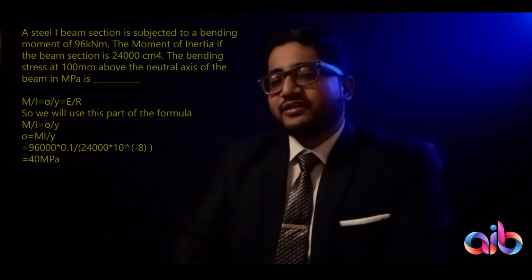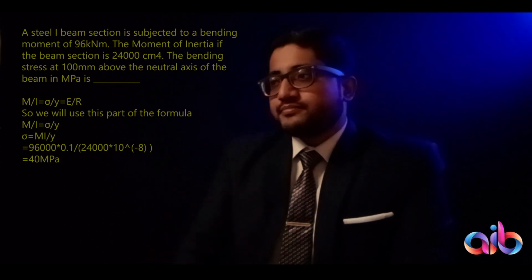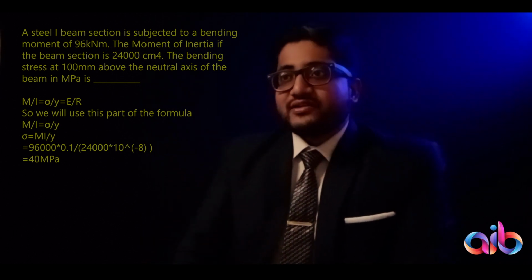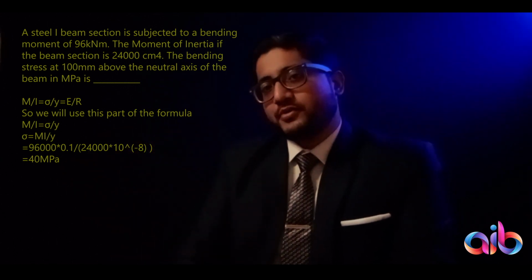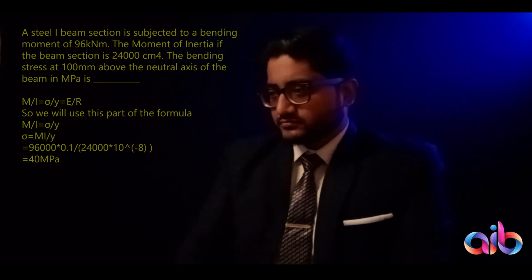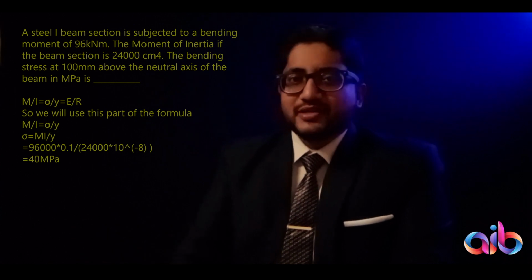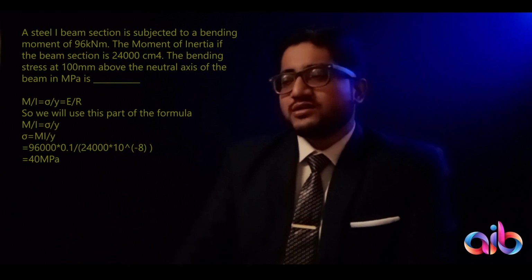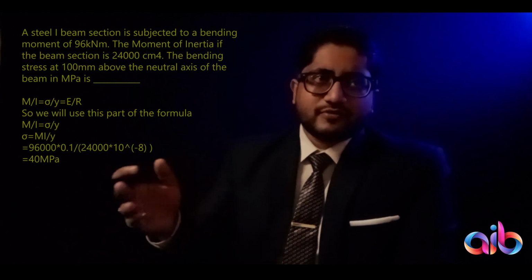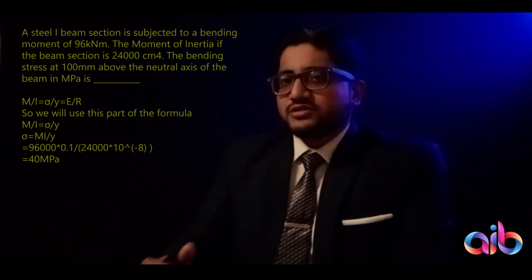Anyways, for these kinds of sums, the concept of bending theory, bending stresses, the neutral axis, and even limit state of collapse and how bending occurs, etc., have to be proper. Once that is done, you just use the formula M by I equals sigma by y equals E by R. You just put in the numbers, whichever is given. There are two equal-tos in between. So out of 6 quantities, 1 or 2 would be unknown. So you just use the formula and get the answer. It's very simple, nothing much.